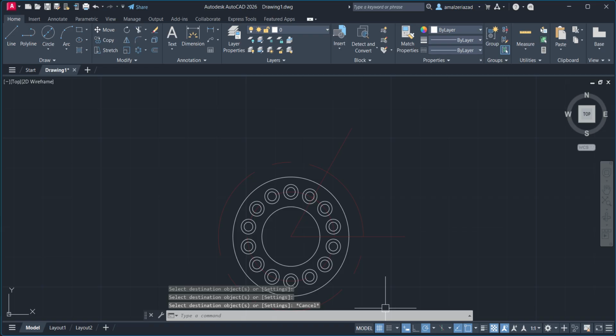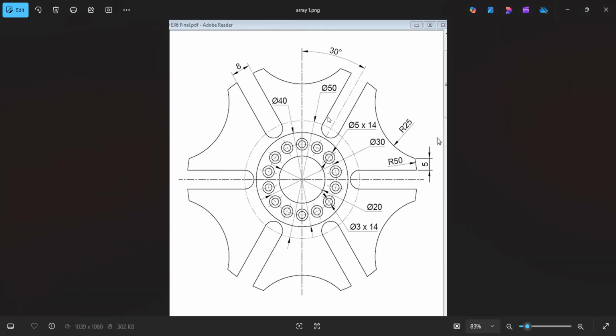Then if you can see here, there is an offset. From this line, it is not exactly on this line. Here there is an offset, so that gap we have to check. Here, if you can see, there is a gap of 8 mm, right? So an 8 mm gap means 4 mm, half of it. So the same line you can just copy for 4.